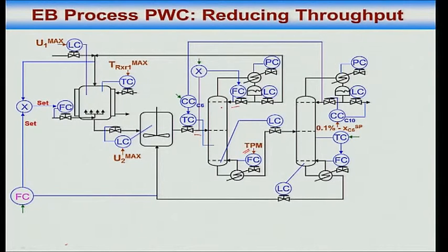Well, if it's active, no. Is it critical to control the benzene leaking down the first column? Yes, because otherwise it will contaminate my product. So even though V1 max is active, I still need to control it. Therefore, this loop has to be there, right? It is all coming from what are my constraints that are active. The structure is following from that.